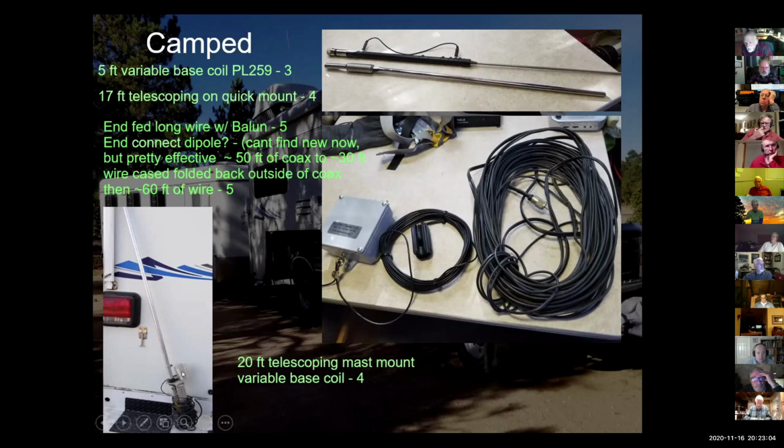And that's actually a little bit more work because I have to figure out something to use for a mast to tie it to. I've got one of the military 5-foot section aluminum mast sets that I can run up to whatever height I want. And I've used that with it a few times, to get a nice tunable vertical mast that's a reasonable length. It does a pretty good job.